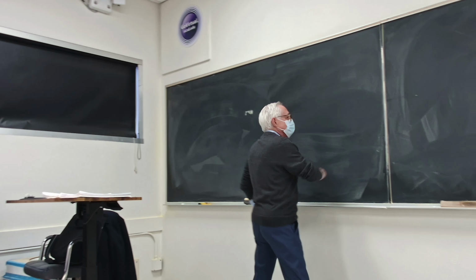So in general, under steady state conditions, just like the other one, I have 0 equal to Q dot control volume, if there is any heat loss from the compressor. This is the control volume around this. Minus W dot control volume, plus H in minus H out, H1 minus H2.